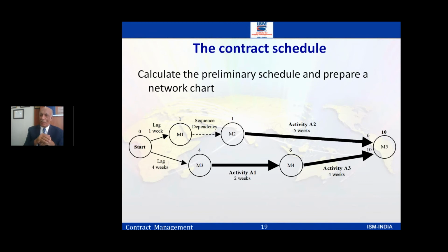While if I look at the upper ones, because I'm doing two parallelly, but in real life you may have many of these offshoots around. It's the most simple one. I've tried to draw it around. So in the upper one, when I go from M1, M2, M5, the total is 5 plus 1 weeks. So I have got extra time around. So even if there's a delay in that path, my whole schedule time is not disturbed.